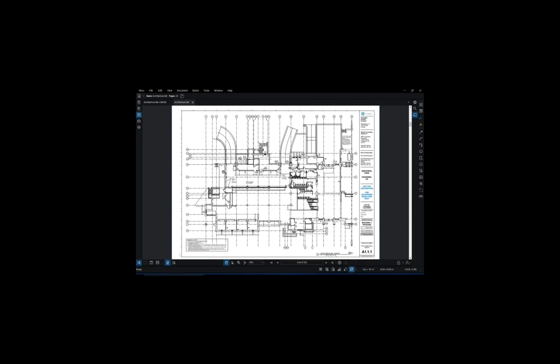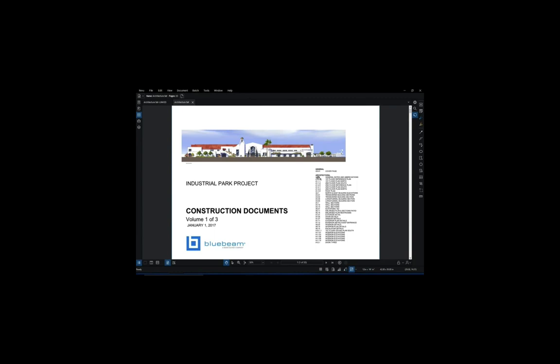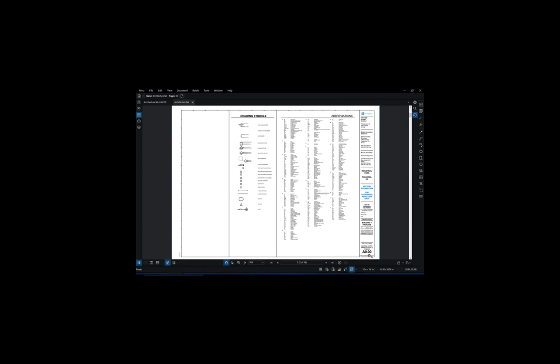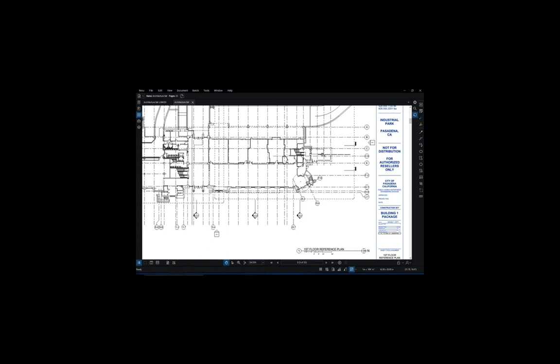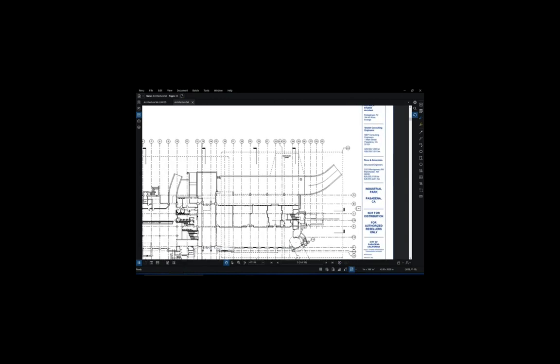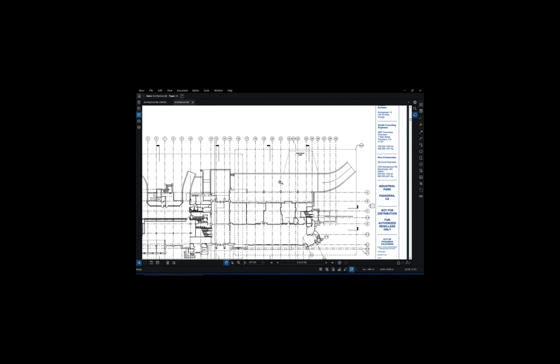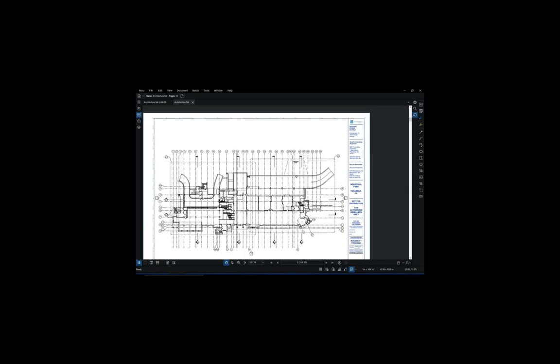So the Batchlink command in Revu Extreme is going to make navigating a set of drawings so easy. What it does is it scans an entire drawing set for things like sheet numbers on a drawing list on the cover page. Then it searches for sheet numbers located in something like a title block, and then it hyperlinks them to things like elevation markers, section markers, and detail callouts, so that when you click on the callout, it hyperlinks you to the corresponding page in the document, much like you'd find in a hyperlink on a website. So when you click on a detail marker on the floor plan, it brings you to the corresponding page without having to dig through the sheets manually.